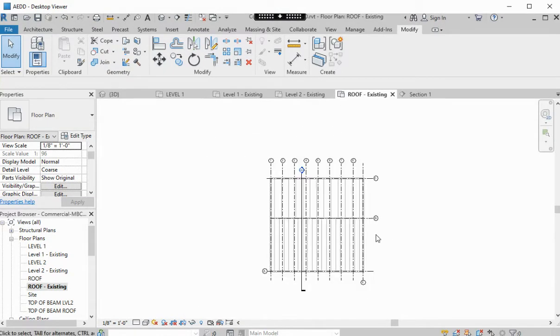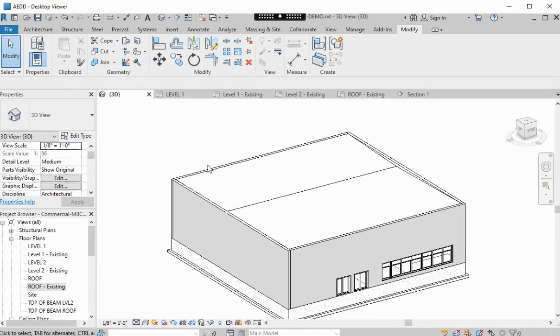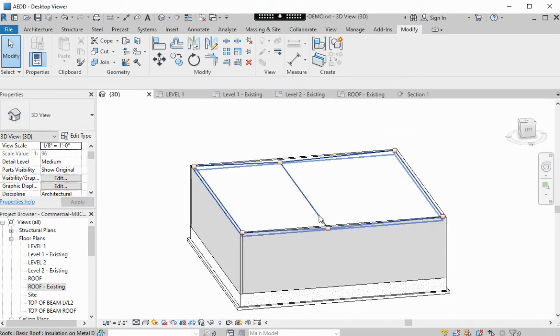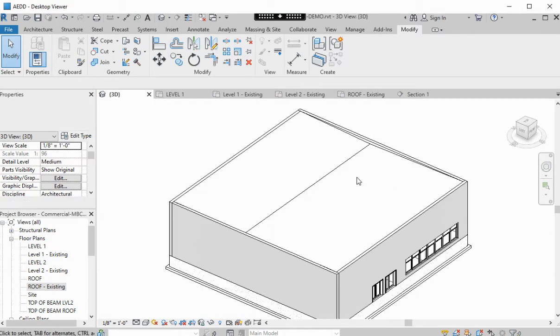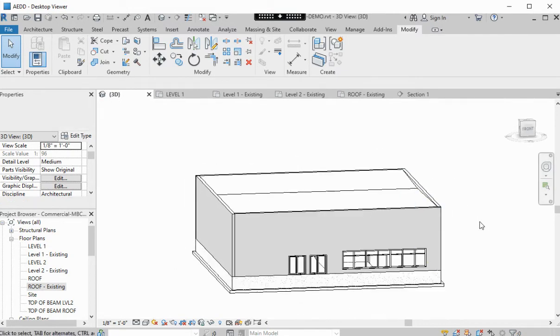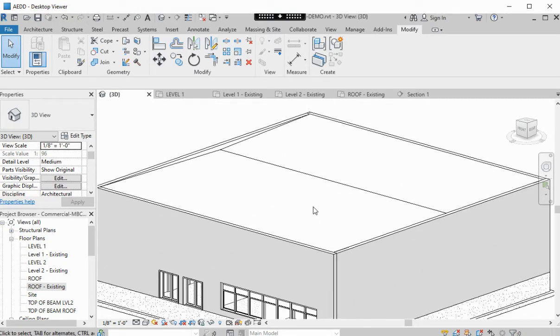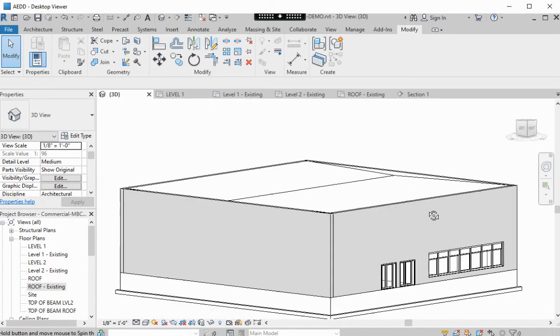This is a really common roof system to see, and where the tapered insulation reduces down to that 5 inches, this is where the roof drains would be, which would make sense to have the roof drains in the center where they could go down through the wall system that's going to be staying put and then be sent outside of the building somewhere. So it drains that flat roof. No roof is truly ever flat. It usually has some kind of tapering like we're seeing here, or some kind of slope that directs the water to a location and drains that roof so that it is not a truly flat roof.